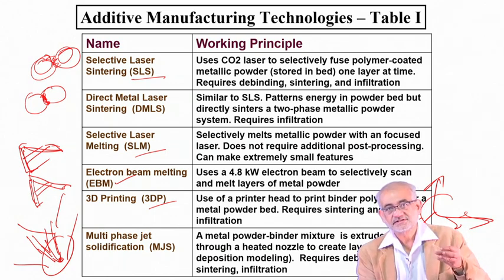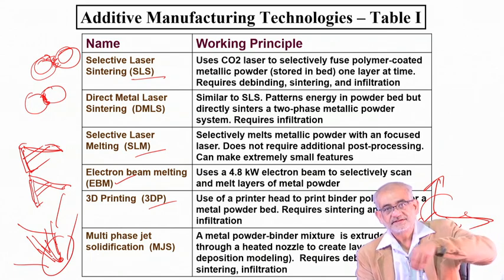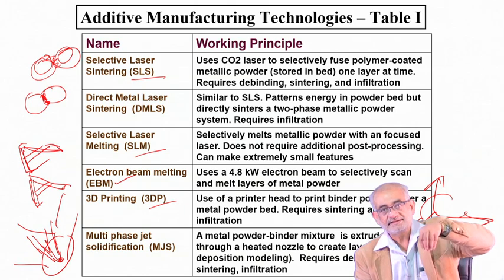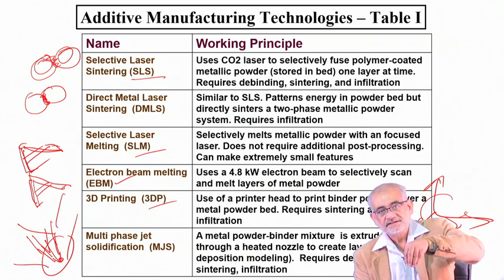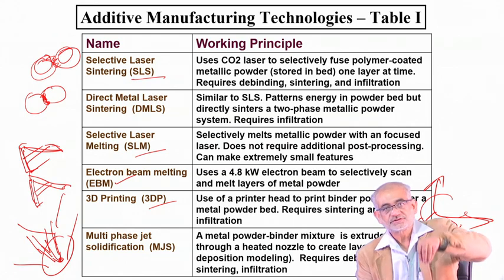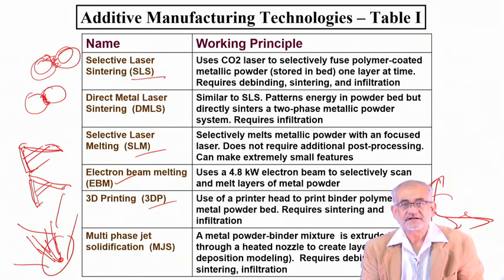So the arm can rotate, move, and translate and create. Essentially this robot arm will carry the laser beam, the powder feeding system, and the concentric nozzle, and both will act simultaneously. And if it goes through a circular, vertical, or lateral motion in X and Y direction, it can create practically any shape.